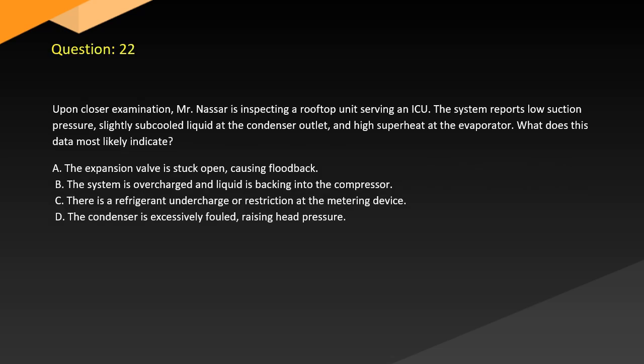Question 22. Upon closer examination, Mr. Nasser is inspecting a rooftop unit serving an ICU. The system reports low suction pressure, slightly subcooled liquid at the condenser outlet, and high superheat at the evaporator. What does this data most likely indicate?